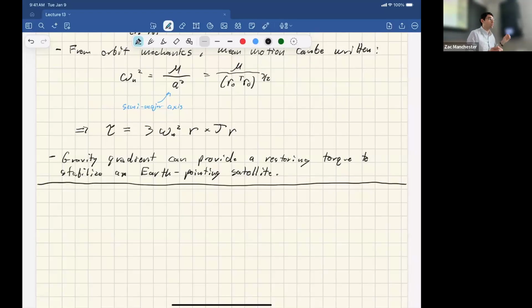And the gist is you want to, in an unsurprising way, and I'll foreshadow slightly, basically want the long axis, the major axis, the long dumbbell axis, oriented in this radial direction. And to get there, the recipe is the same one we've done with the Euler equations to look at stability. We're going to write down Euler's equation with this stuff plugged in. Then we're going to linearize about some nominal attitude and check eigenvalues and make sure things are pure imaginary and that there are no positive real parts that are going to blow up. It's the same recipe.